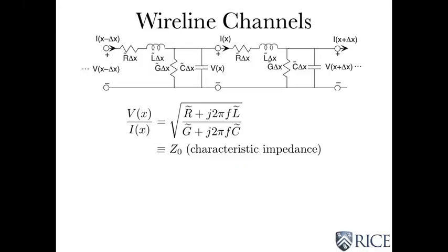All right. Now let's worry about that ratio that I mentioned, the impedance. So this ratio, which we just saw, is called the characteristic impedance of the cable, and it clearly is frequency dependent and also depends on the component values that well describe a piece of coaxial cable of interest.